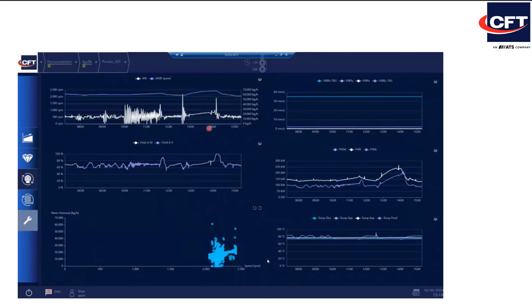But most importantly, what we do see is also the yield of the compressor. That is the ratio of the energy which is absorbed by the fluid, in this case the vapor, divided by the energy that was absorbed by the motor. And we can see that this efficiency was fairly low at 60%, and only once we raised the speed of the compressor toward its nominal values, that efficiency was able to rise at 80% and above.